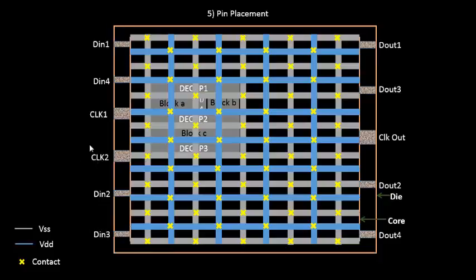And there are reasons why we placed them not in an ascending order fashion, but in a location something like this. For example, if D in 1 is over here, D in 2 lies over here. There is a reason we have done it, and we will be explaining that in the following sections. But the next step of the floor planning is pin placement. And the pins are also located close to logic, that we'll be seeing over here.